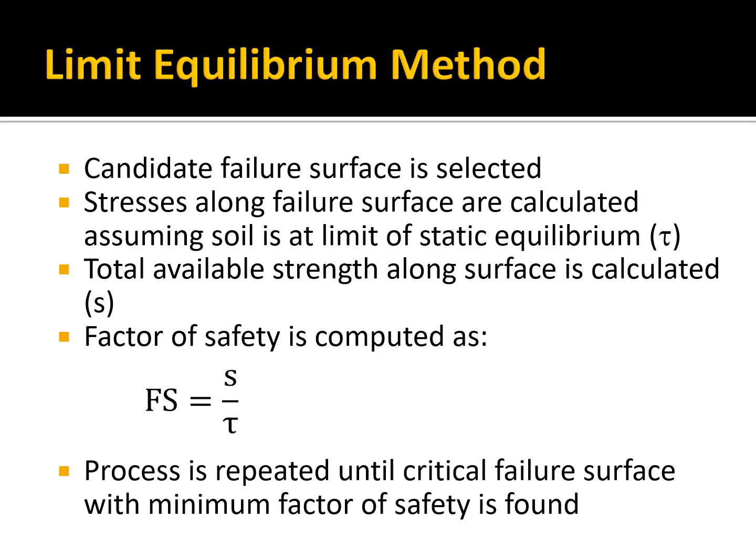So any factor of safety less than 1 means the slope would likely fail along that surface, and a factor of safety greater than 1 would mean it would likely be stable. Now, in design, you typically want a factor of safety of at least 1.2, preferably 1.5, something like that. The higher the better. But often when you're designing a slope, you're deciding how steeply you can cut a slope. So let's say for an embankment next to a highway or a cut or a fill area, then you want to...